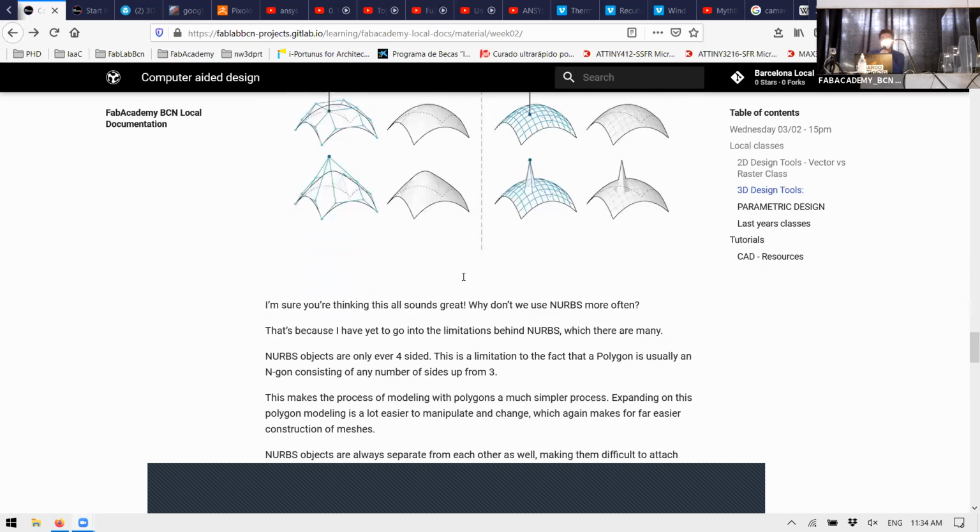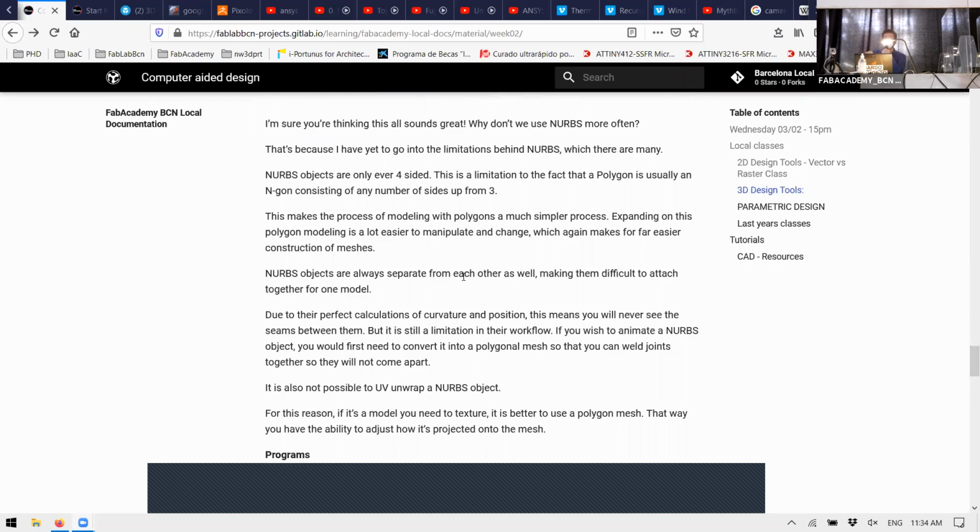For example, programs like Rhinoceros work with NURBS and meshes. There is always one kind of format that they are better with than the other. Usually, Rhinoceros is better with NURBS. So when you work with really big meshes, it has problems with memory because it's a program designed to work with CPU, not with GPU. Other programs, for example, Meshmixer, is a program that is specifically designed to work with meshes. So it's way, way faster and it's way, way easier to edit.